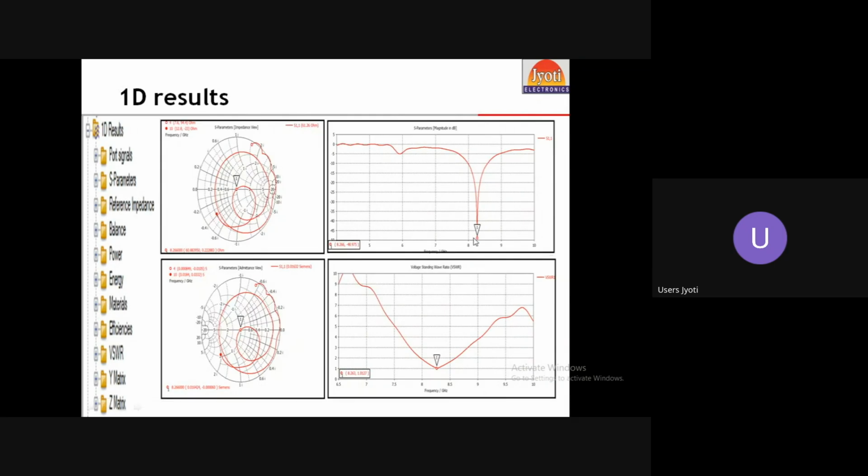You first select the frequency from the S parameter and you can see at 8.26 our antenna is resonating, and for that frequency you can analyze here how the impedance is. Here it is 60 ohm, slightly mismatched. You can optimize the design and the design geometry. So after that you can analyze our results.